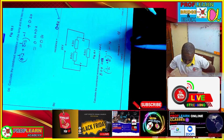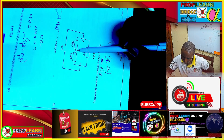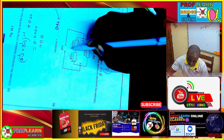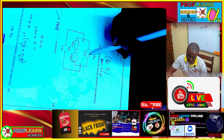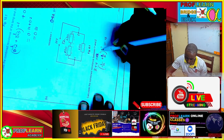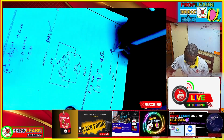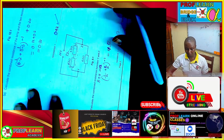The next one we have is two resistors here which are in parallel, and two resistors here which are in series. Then we are going to add these two together, and if you combine these two, you are going to get 12 ohms. Then that 12 is in parallel to this one, so we are going to say 1 over 12 plus 1 over 6, raised to negative 1. If you work it out, you are going to get 4 ohms. So we have 4 ohms as the total resistance for this particular connection.